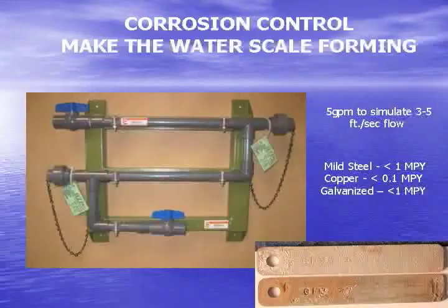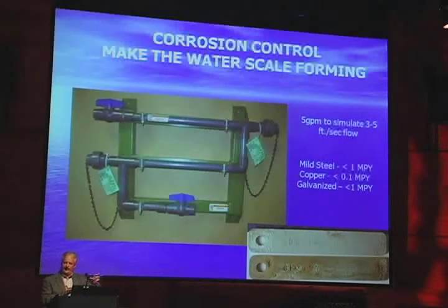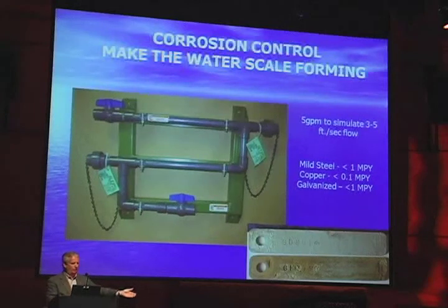Okay, corrosion control. We don't really do a whole lot when we have scale forming water. If you look at water, it either wants to be corrosive, it wants to take minerals to satisfy itself to be stable. There is a point where it's actually stable. These are where the nuclear power plants run. People that run water out of Great Lakes and run into nuclear power plants for condensers, they can't discharge that water back to the Great Lakes with chemicals. They can't discharge it to the groundwater. So what they do is they actually adjust the water quality so it's very non-corrosive, non-scaling. It's right at that middle point. Now that's difficult to do, but they have the time and the resources to do that.